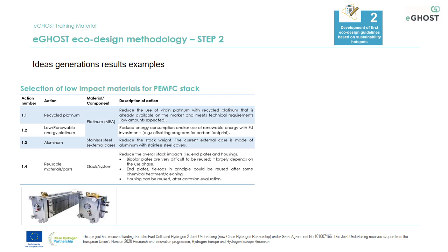You have here some examples of idea generation results. So these are some eco-design ideas for the selection of low-impact materials for the PEMFC stack. For example, you have some ideas related to the recycling of platinum, in order to reduce the use of virgin platinum by using recycled platinum that is already available on the market and that meets technical requirements. You have also some ideas related to the replacement of stainless steel by aluminium in order to reduce the stack weight.